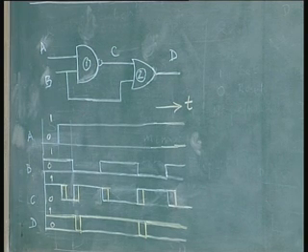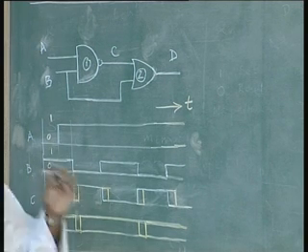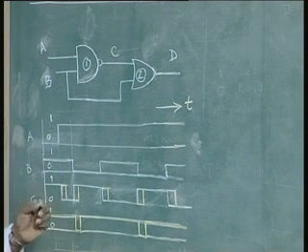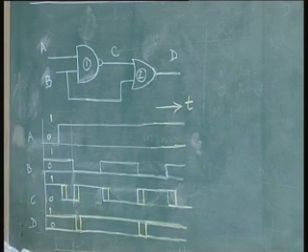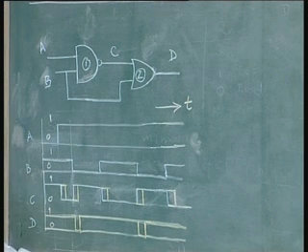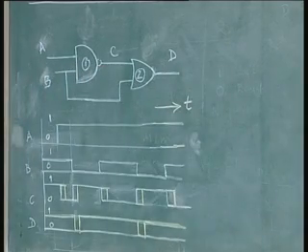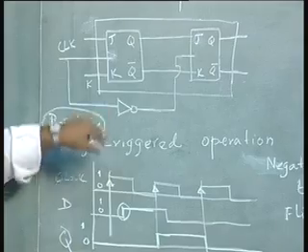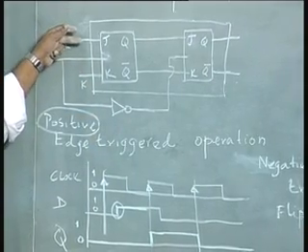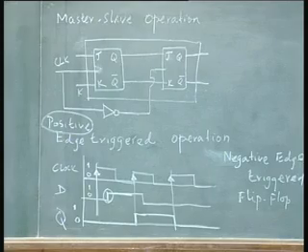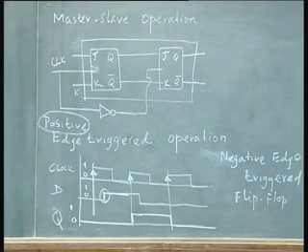We said that the edge of the clock determines the operation. Only during the clock edge will any input be recognized. It is easy to say, but how do you implement it? Because when you have a flip flop of JK type here, we have inputs occurring and the clock occurring, and you cannot suddenly remove one of them and say it is only for a short duration.